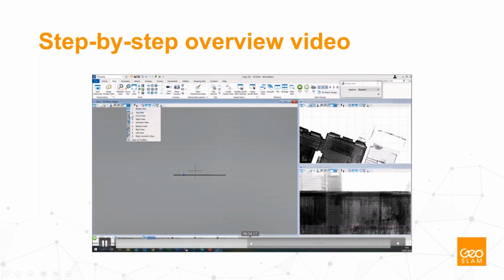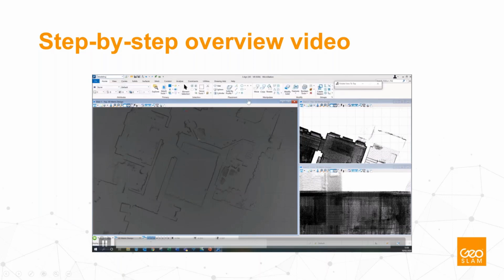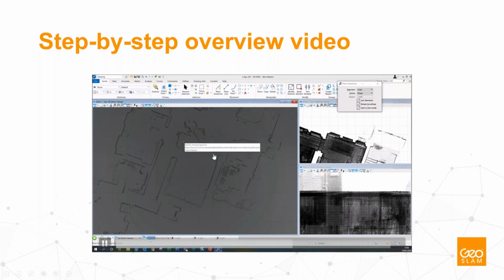So you can select top view and start creating lines. Again, in this case, it's important to change the ribbon to drawing and place the smart line, which will then follow the point cloud in a similar way.